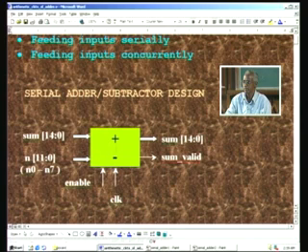We have basically 2 numbers added here, and in fact all the 8 numbers are going to appear through this input, whereas the accumulated result will be available in a register. Internally there is a register, and that is what is output here as sum. Since we have 8 numbers of 12 bits each, we need to have 15 bits totally, and the difference is that 3 bits between the input and this one.